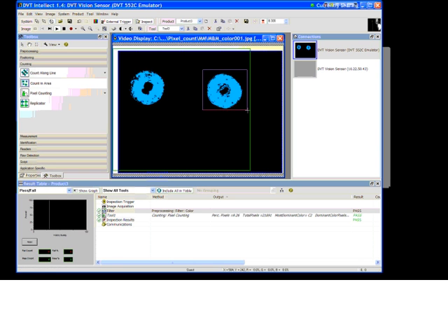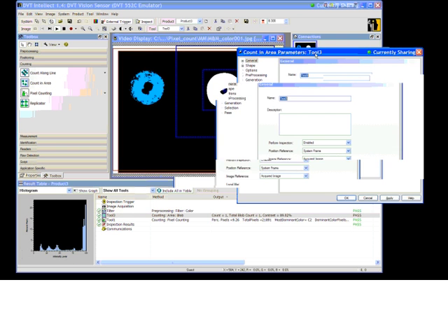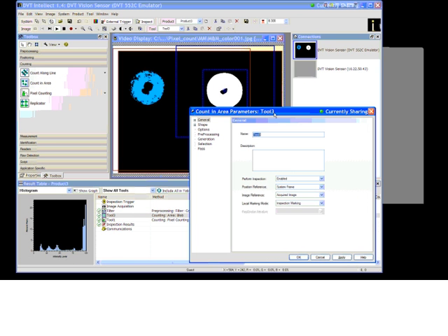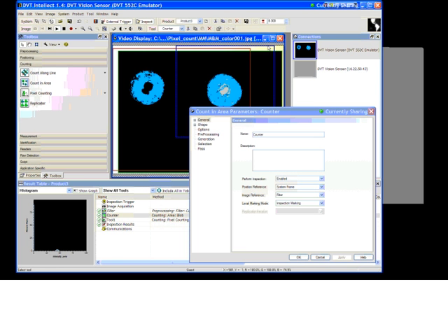So right now we've created another image through the filter tool. What the filter tool does is create a new image based on an input. And what is that input? The input is that color information from the pixel counting tool, and for that specific color within this pixel counting tool. So right now we've just created a new image, and this counter or blob counter under image reference will use that filter, actually reduce my region of interest so that it's within our filter.